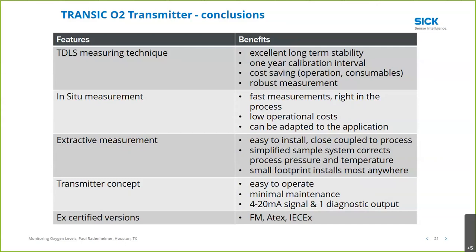Do filters impact the response time? Absolutely, they do. The most ideal situation is to have no filtration and just a sample flowing through the sample cell, which is open on all sides. That gives you almost instantaneous response. Adding the screen will add a small amount of time to that, so you might have a 10-second response.